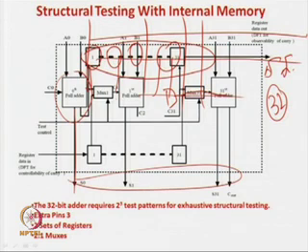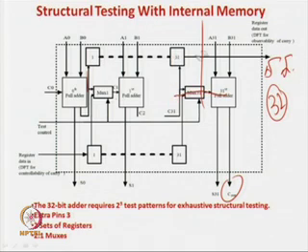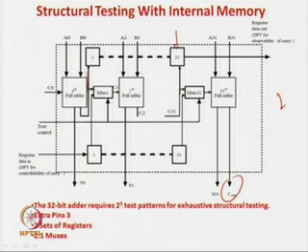So, 32 clock pulses will be required, or on the order of 32, you can forget about the last carry bit. They have to be shifted out. Still you cannot say that I have totally done away with the pin business, because we require one extra thing: a clock for this shift register and a pin to bring it.